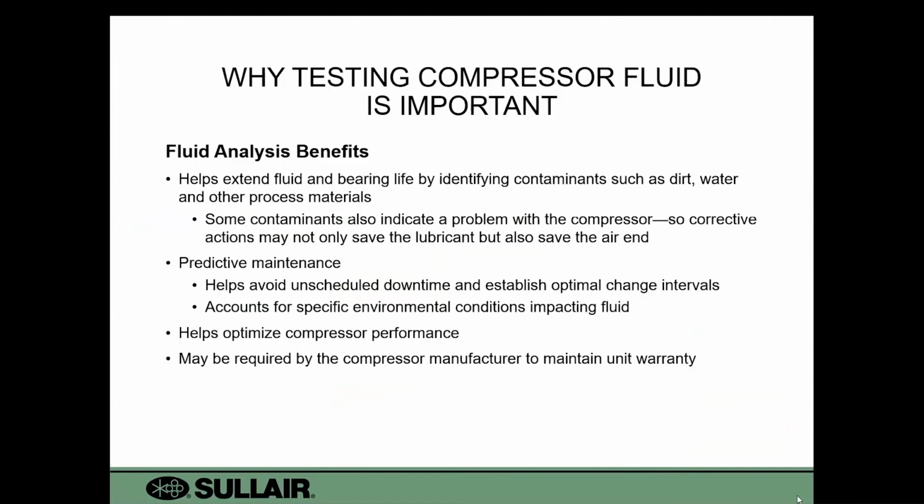Now, sampling your fluid is very important. It's recommended to do it annually, but there are a lot of customers out there who do it quarterly so they can keep good track of the performance of their fluid. You want to make sure it's not deteriorating, it's not going acidic, it's not forming varnish. You want to identify it for predictive or preventative maintenance so that you avoid any unscheduled downtime, any unnecessary damage to your machine, and it also helps optimize the compressor.